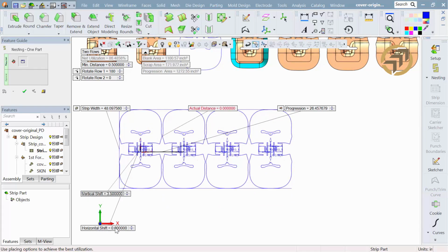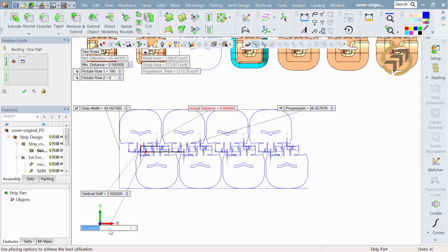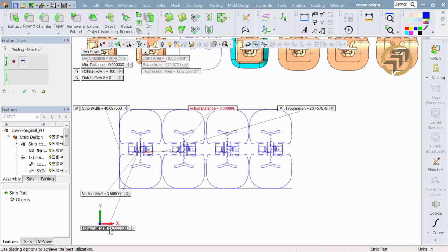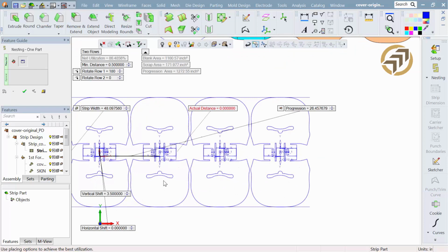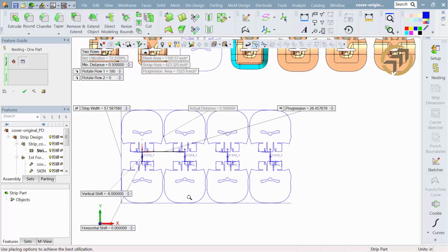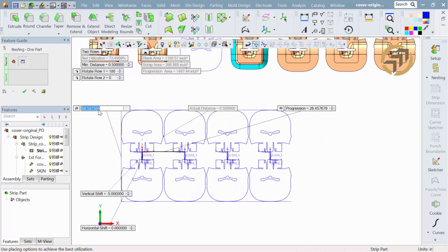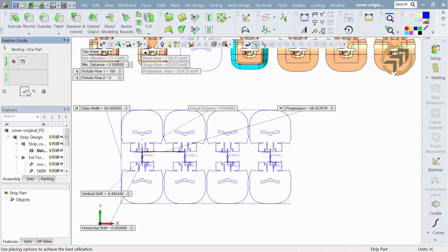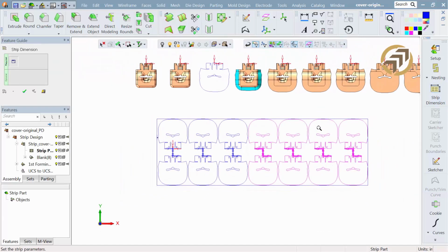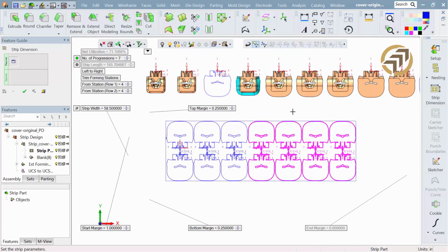Now maybe here just playing with it so you can see a few things. Perhaps try to force it to shift so that it intertwines like you see here. An attempt at that might be to keep the coil width narrower. Here we're going to set it up so that we have our different stations opposed to one another. So I'll either decide on the actual distance in between, or maybe I want to change the overall width so that that's the coil that I would order, whatever the preference is. So it's important to know there's lots of easy to use tools for setting up the nesting.